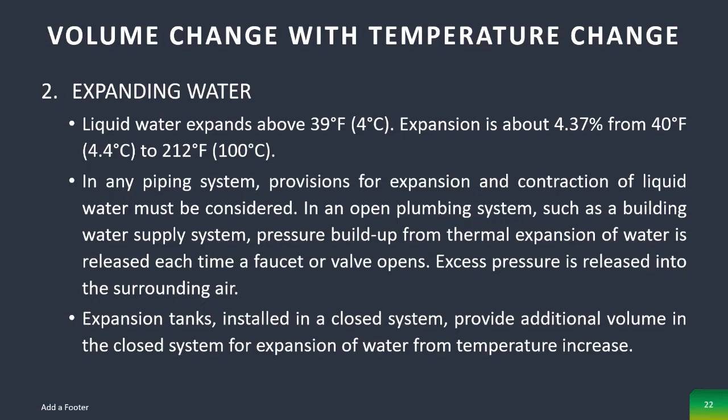In an open plumbing system such as a building water supply system, pressure build-up from thermal expansion of water is released each time a faucet or valve opens. Excess pressure is released into the surrounding air. Expansion tanks installed in a closed system provide additional volume in the closed system for expansion of water from temperature increase.